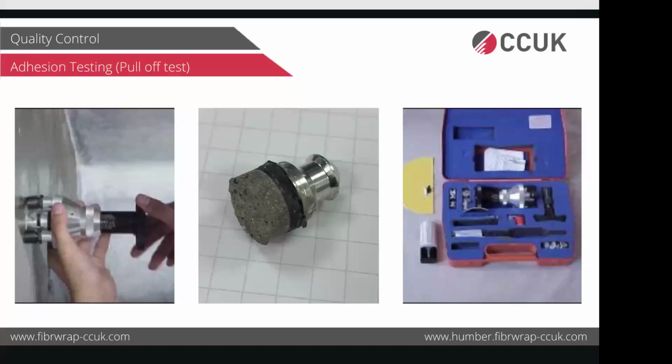Now the difference between this pull-off test and the concrete pull-off test is that in the concrete pull-off test, we look out for a strength in terms of a number, like whether it's 3 MPa, 4 MPa, depending on the grade of concrete. But in FRP, we are not interested in that number. We are more interested in the mode of failure. What we want to see is that when you do this pull-off test, it should not come out from the substrate only, or it should not come out from another layer of FRP if there are multiple layers.